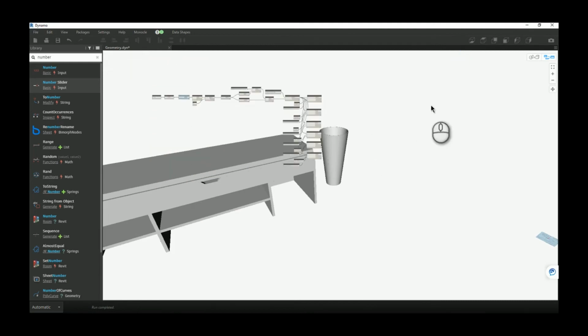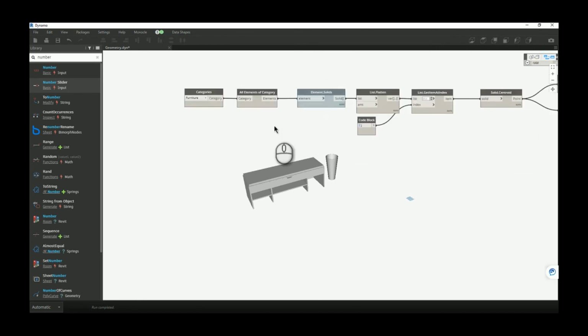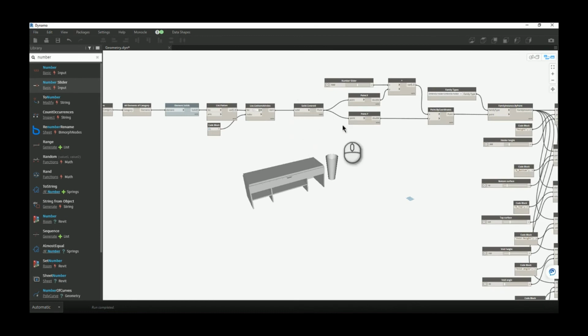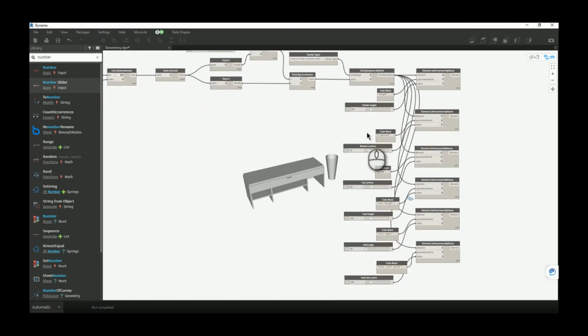And basically that's it. Let's recap one more time. So in this video we learned how to convert an element to a solid, how to find some reference point, how to create a new point, and after all of that we learned how to insert some new family inside our project. And if you create that family in a way like I did with this holder, so I can play with parameters and geometry, this is the way you will link all those parameters, and easily with these sliders you can pretty quickly create the end product.